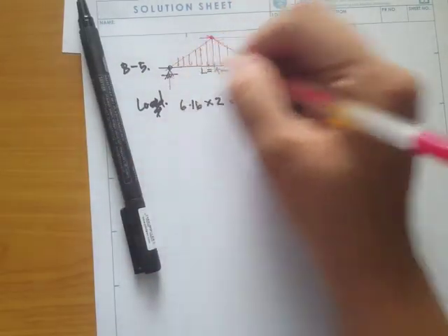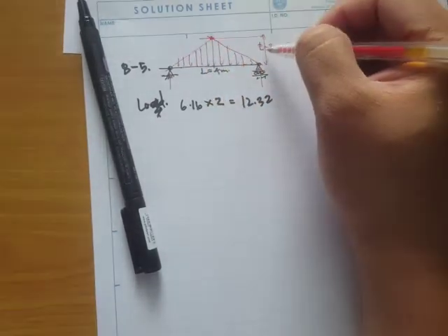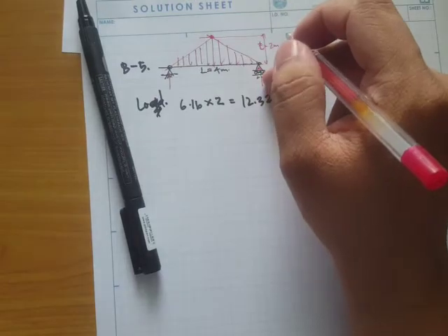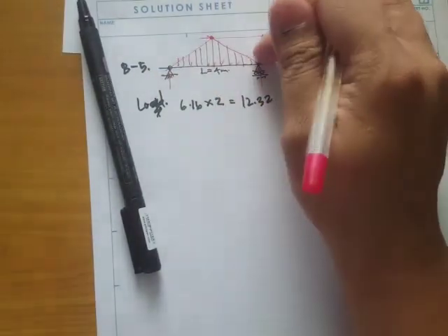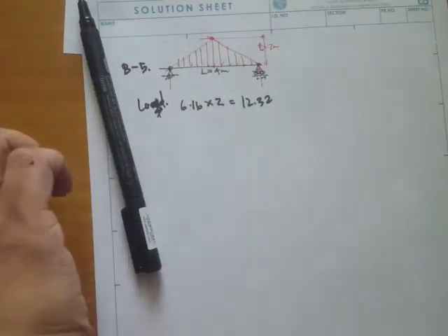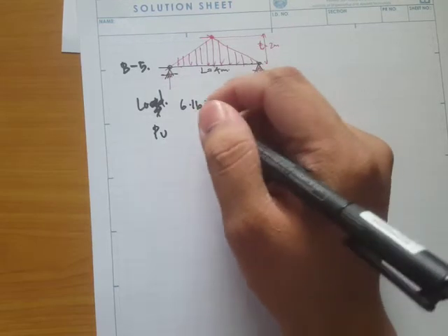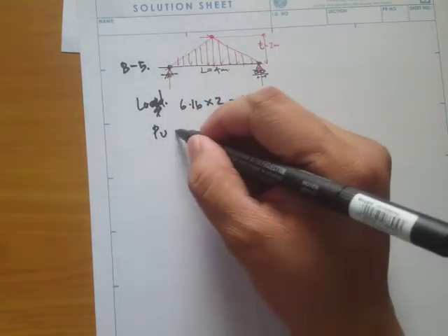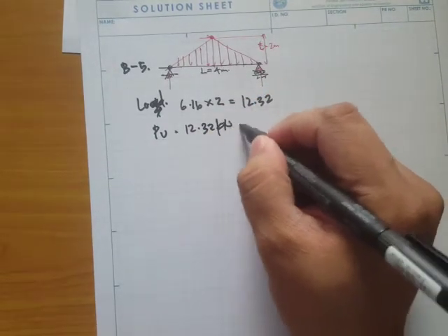So if you try to solve for the support reactions, let's not simplify it. Let's not make it rectangular. If you solve this, using the appropriate equations for the shear under these beam conditions and loading conditions, what you get is a support reaction having a value of 12.30 kilonewtons.